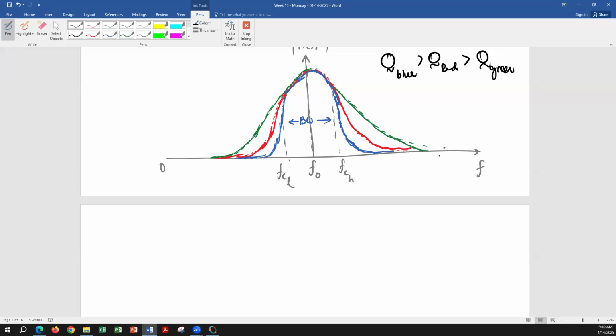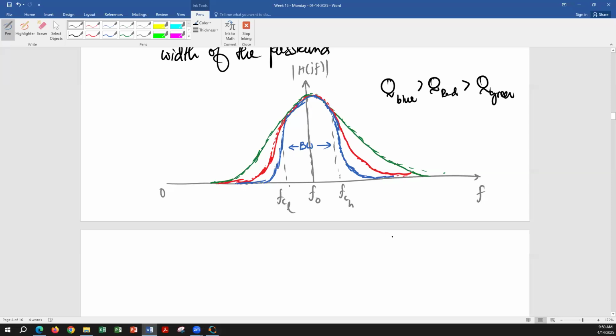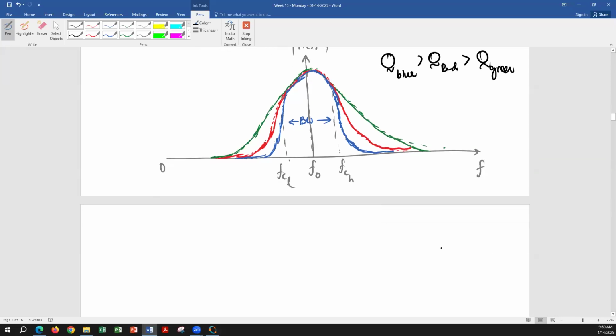In that, we're going to study the active filters: active low pass, bandpass, high pass. We discussed low pass and high pass, maybe not bandpass. But anyways, you can get the idea from low pass and high pass that when we increase the order of the filter, so we add more operational amplifiers, then that transition band is getting steeper and steeper. The circuit starts becoming complicated, but it starts becoming more selective. In this case, we will still be doing the second order filter, but we can change the component values to get more selectivity out of the filter.